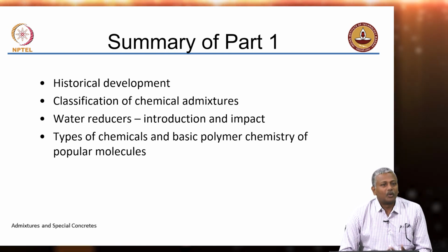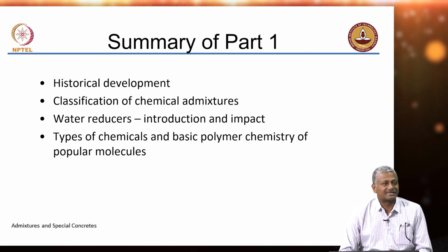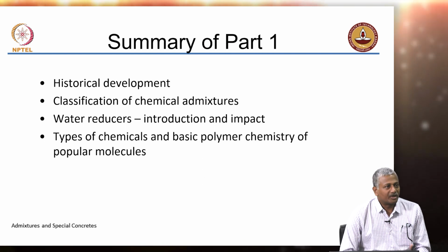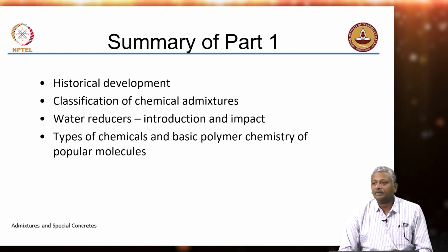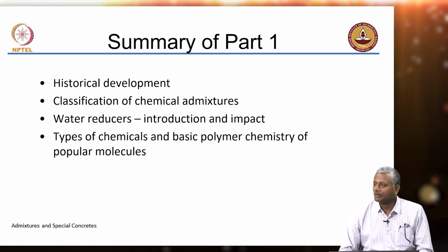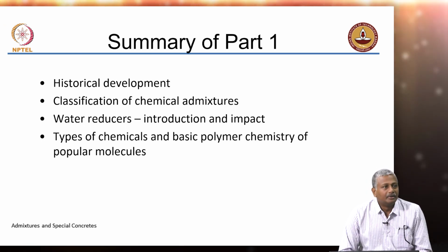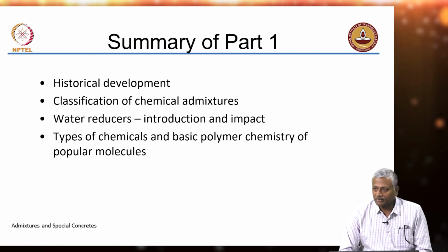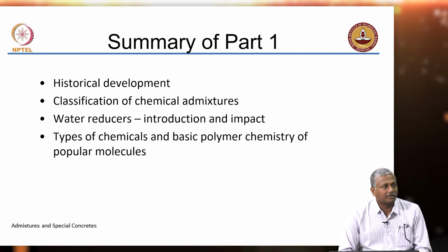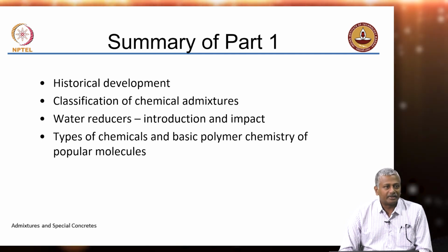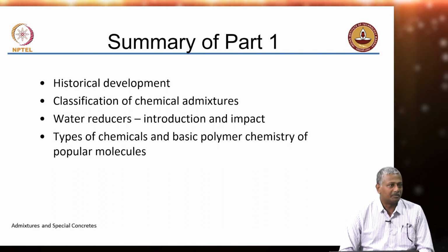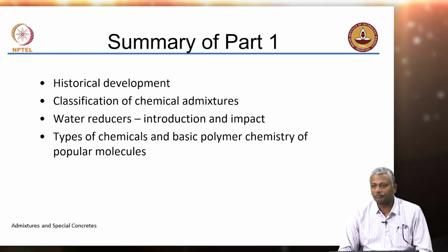We started talking about the introduction about water reducers and the impact that they can have on introducing sustainability in concrete. Why do we say water reducers are introducing sustainability in concrete? What was that one factor that we talked about where we can actually introduce sustainability in concrete by the use of water reducing chemicals? Reduction in the cement content. Yeah, that's the primary impact. When we have water reducing chemicals, we can lead to a reduction in the overall cement usage, and that will contribute in the best way to the reduction of the overall carbon footprint of the concrete.